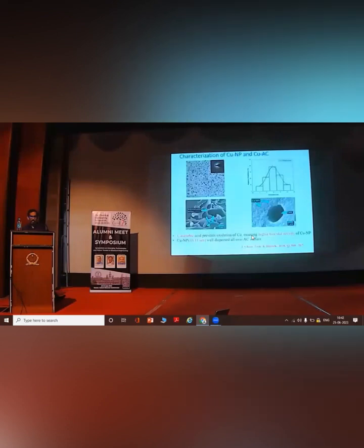So we did all that, and just to illustrate, for example, this is carbon, which is used in our filter media, with a large number of pores, which are used for removing color, odor, and smell, and chemicals, but not E. coli, because E. coli feeds on the carbon. So you need to put something else. People have UV power switches, but when there is no power in rural or other areas, is there any additive that you can use? One additive which we have tried is copper and silver combination.